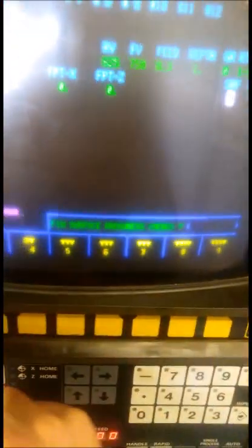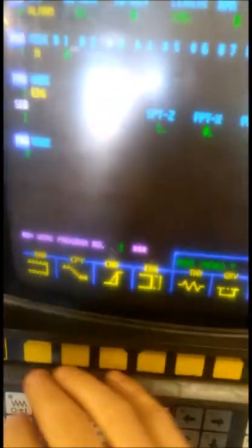And then you've got surface roughness. This calculates basically what your finish cut's going to be, the feeds of your finish cut. So I'll just set that at 8, so I want this to look pretty.